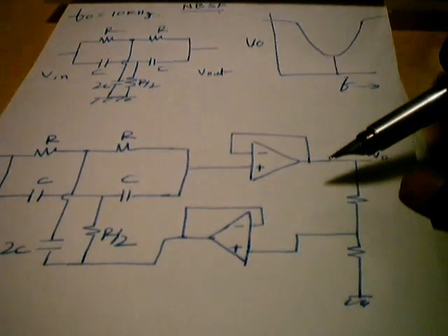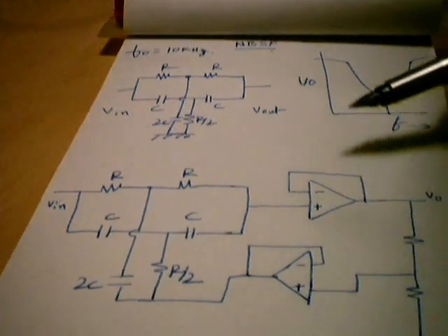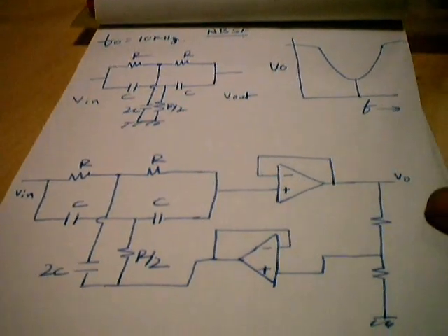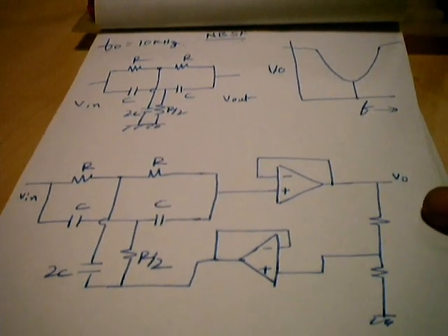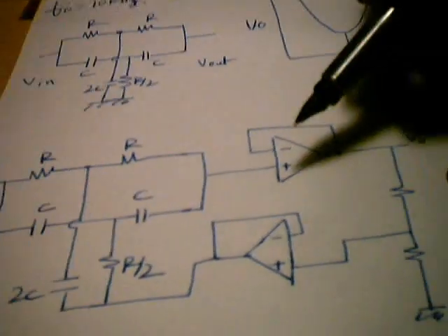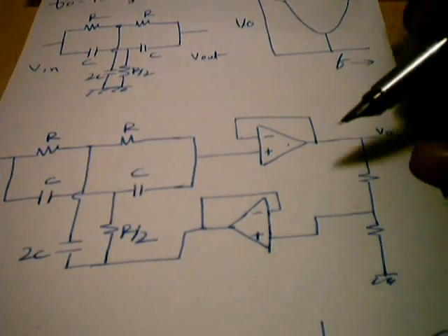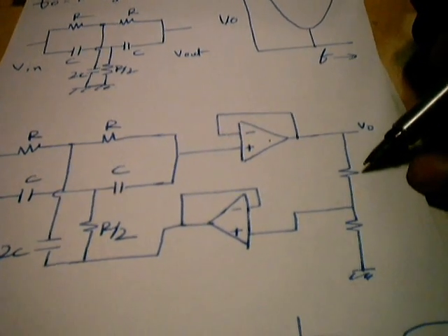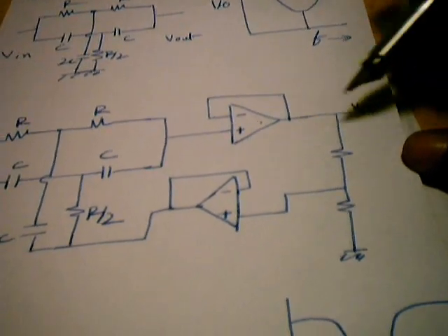You can see this is a modified circuit of the same band stop filter, which we'll now call the narrow band stop filter. Why? Because the bandwidth is reduced, which eventually increases the Q factor of the circuit. This is one emitter follower, this is the other emitter follower. The resistors RX and RY will decide the amount of feedback we are giving.